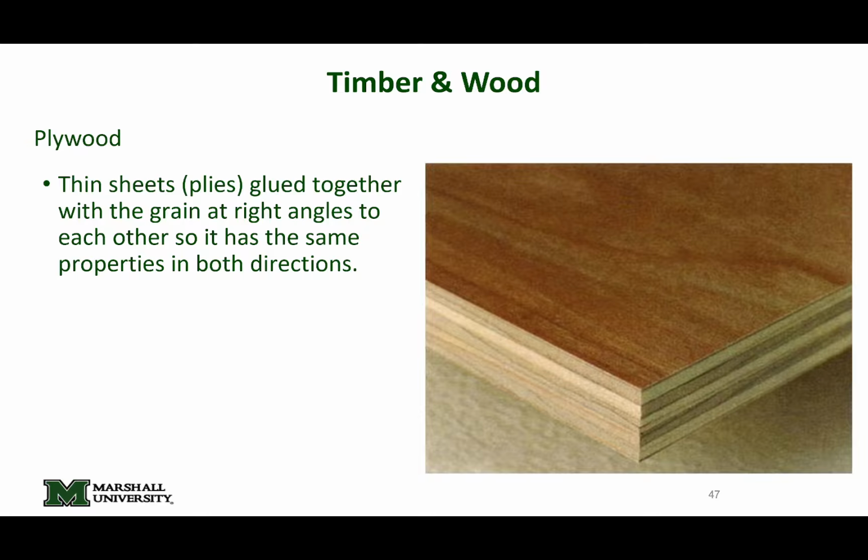The tree just shucks out. Then we take the plies and lay one like this, one like that, one like this, one like that. Suddenly we have a board that behaves largely the same in one direction as it does in the other. Simple.